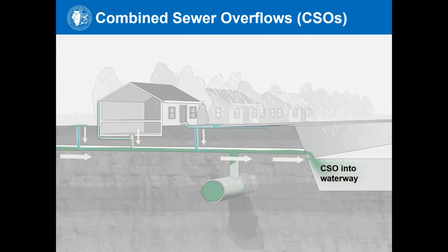So, as I mentioned before, the direct connections from the sewers to the rivers are still in place. These were left to protect areas from flooding during wet weather, but as the city continued to grow, combined sewer overflows, otherwise labeled here as CSOs, became more and more common. So by the 1960s, CSOs were happening around 100 times every year, and they were having a negative effect on the local waterways.